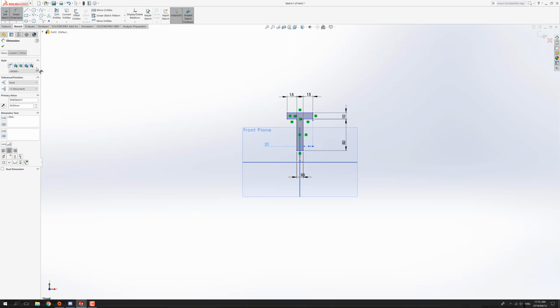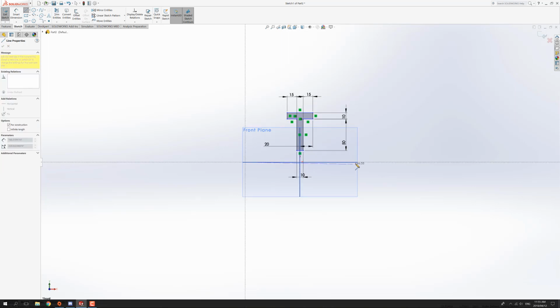It's easy, just go here to the drop down arrow, add line, and there it says center line. So just click center line. You make your center line somewhere here on the center, just makes it easier. You see it automatically snaps to something. That's when you start drawing, it will give you some relations of its own. Okay, so we're adding the center line.